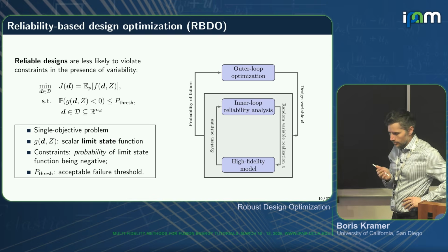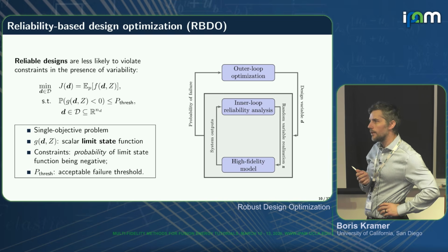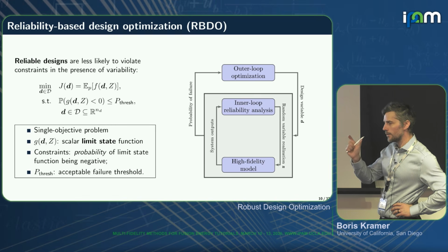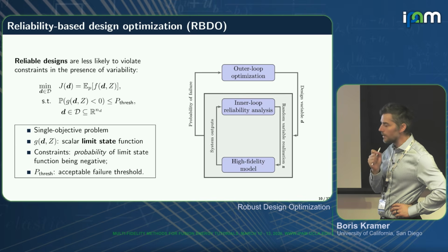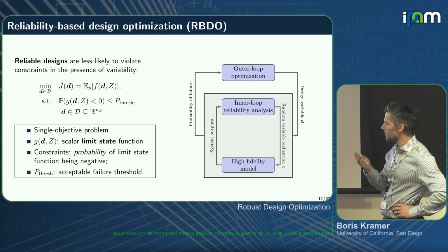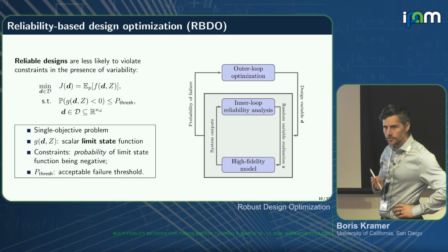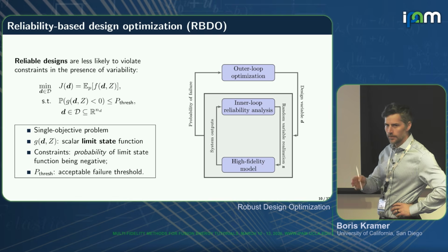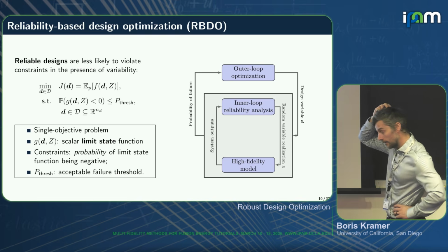Then you have a second framework to deal with things, or another one. This is called reliability-based design. So in robust design, you put the uncertainty in; you want to design so that the quantity of interest or your cost function has minimal variability and drives you to an optimum in the mean. In reliable designs, you're trying to minimize the cost, but you really care about the constraint violations. So if you have hard constraints and you say, that wall cannot be hotter than X, or at the core we can't have more impurity than Y, or something like this, then you should put it into a constraint.